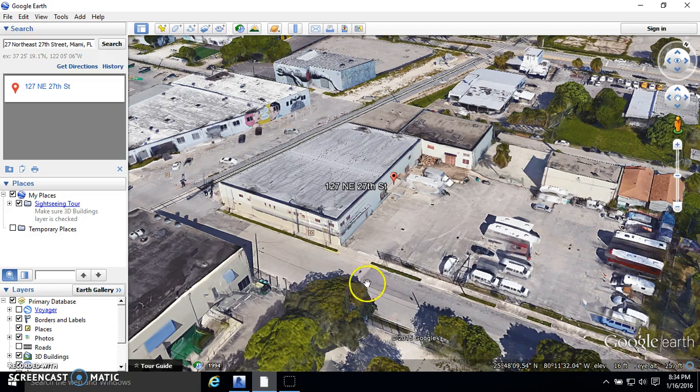So right now, hovering over the street, it's saying 16 feet, so that's a 16 foot base elevation, and when we did ours, we came up with about 12'6". That's the kind of thing that's a little bit off with the contours. As I said, if you had contours every 2 feet instead of the 5 foot contours I had, we'd be a little more accurate. But for this purpose, we're bringing the site up to 0 feet anyway, so we renamed it 0 feet for the ground plane, so it's not a big issue.